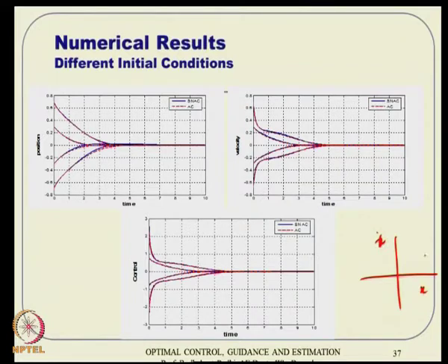What I am looking for is that starting from something, I will go to 0 actually. That is not happening. So, this is something like a closed loop function, and this happens to be a stable limit cycle. That means if I start with anything, I will merge into the limit cycle and then continue oscillating in the limit cycle actually. But ideally speaking, if I start somewhere, I want to go to 0. That is not going to happen unless my control is good. So, that is the problem here.